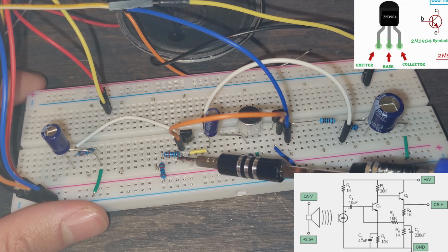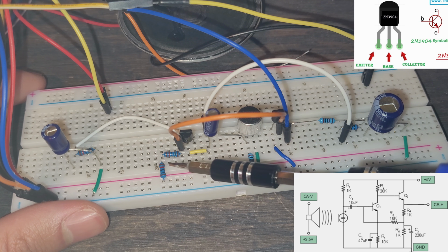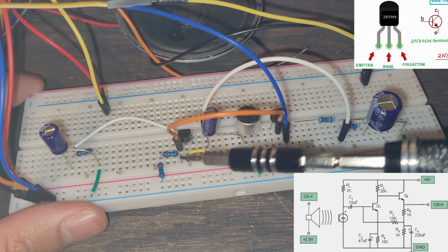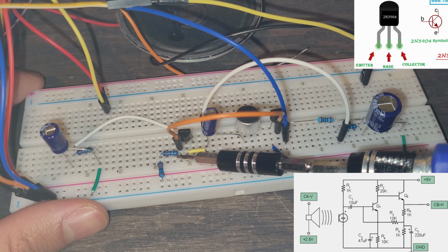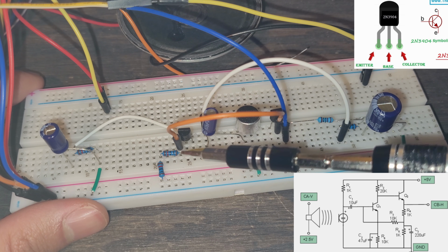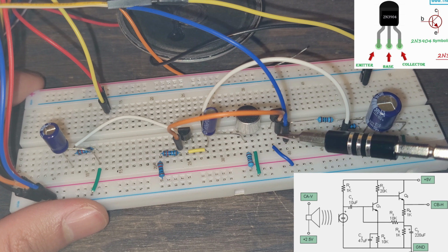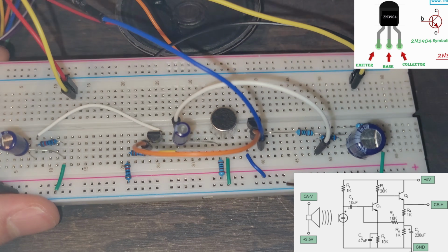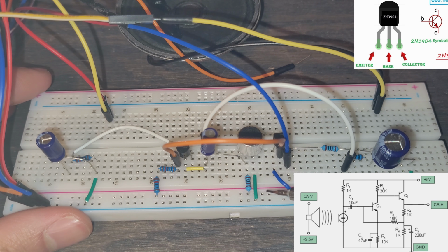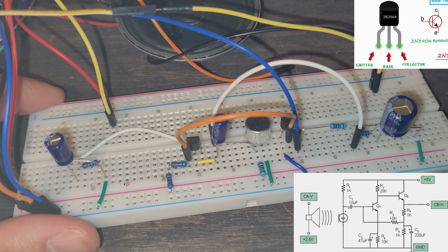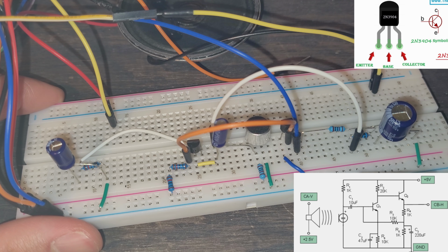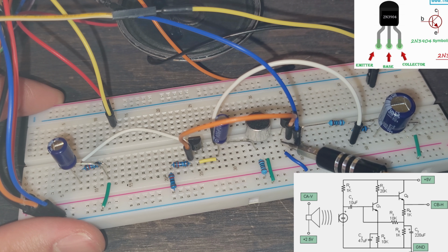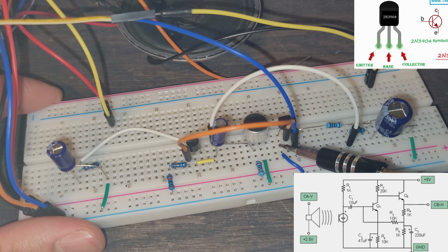When we look at our circuit diagram, it's in the same direction. So the 20 kilo ohm resistor goes into the collector, but there's also a node here because it's going to have this wire that goes from the 20 kilo ohms before it goes into this collector. It's going to go to the base of our Q2, which is the other transistor, which is right here. It goes into this base, which is in the same column, the middle part. So now we also need our Q2 wire to 5 volts, right? Through the collector, as we can see. So this wire is 5 volts, and it goes to the same column as this collector right here. So this is sending 5 volts through it.